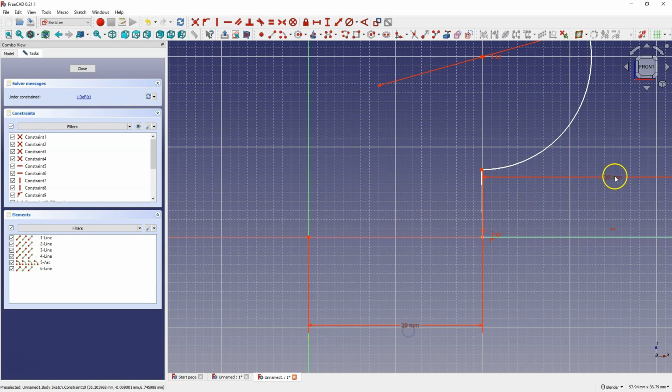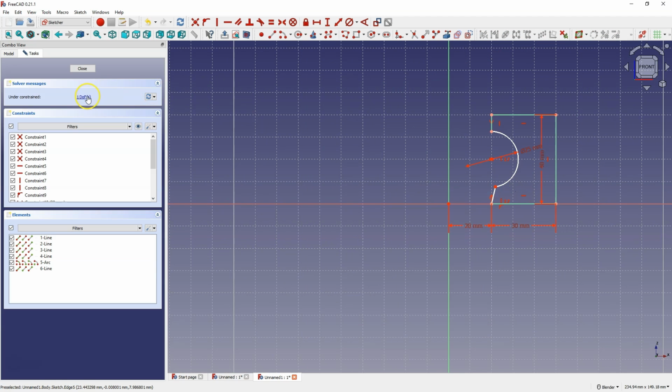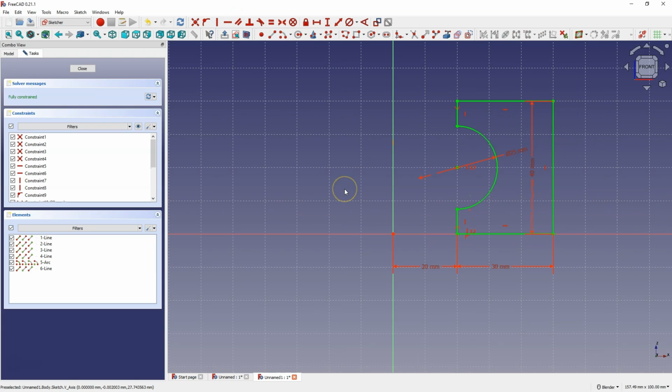However, we are still missing some constraint here, and I see that this line is not a vertical line. Still, even when I click on this point to highlight it, the circle is highlighted. But the point is precisely that at this point, this circle is not constrained. First, deselect this circle. Select that line and select Constrain vertically, and as you can see, the sketch is fully constrained. And that's what you may encounter when you're creating 2D geometry.